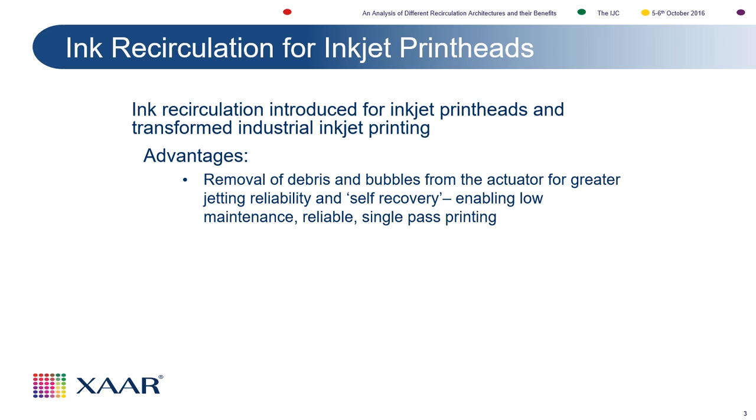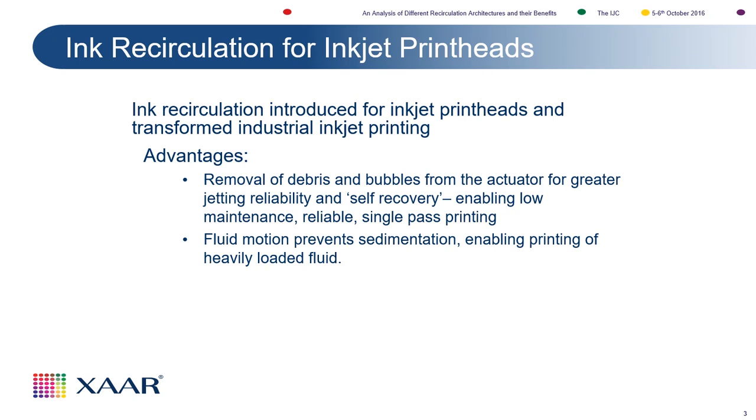It also, and this refers back to some of the previous two speakers, because the fluid is constantly in motion, you don't have any dead spots in the printhead. It enables printing of heavily loaded, solid loaded pigments without the issues of sedimentation and causing the printhead to block.